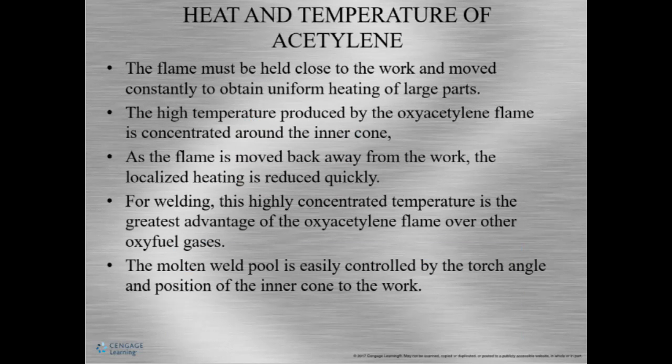Heat and temperature. When we work with an acetylene flame, it needs to be moved consistently to obtain uniform heating of the parts. The highest temperature of the oxyacetylene flame is near and around the inner cone. For welding, the high temperature of the acetylene flame has advantages over other types of gases. When welding with oxyacetylene, the inner cone is used to heat the weld pool.